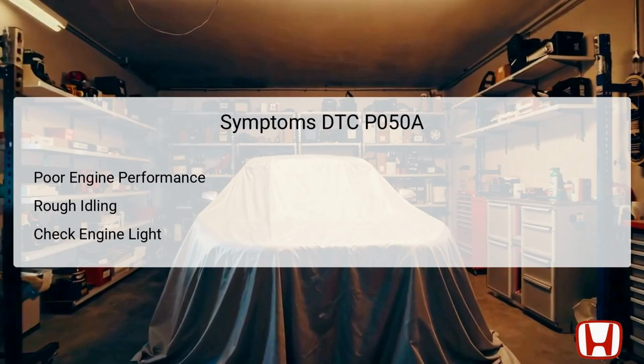The symptoms associated with DTC P050A can range from mildly inconvenient to detrimental for vehicle performance. One major symptom is poor engine performance, particularly noticeable during cold starts when the vehicle is unable to maintain a stable idle. Rough idling is another common experience, as erratic airflow can lead to unstable engine speeds. This fluctuation is often accompanied by noticeable vibrations. Furthermore, the check engine light is typically illuminated, serving as an initial indicator that further diagnostics are required. Other, less common symptoms might include increased fuel consumption or difficulty starting the engine. Recognizing these symptoms promptly is essential in ensuring timely maintenance and preventing further complications.